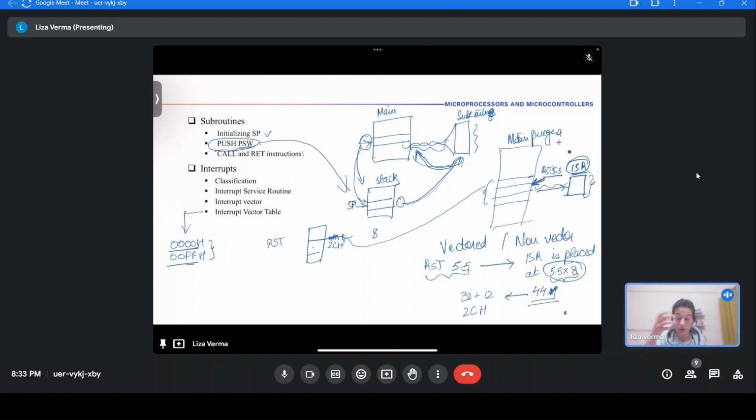So what does a programmer do? Since the MPU has to go to this location that is specified here, in these ISR locations it will point to some other location where the actual ISR is placed, if it's longer than the space given here.